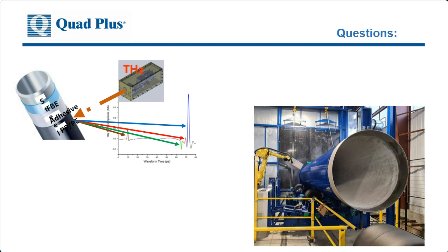Yeah, I think that's generally the case. Obviously with the metal pipe that we're seeing here, it would not be possible to measure the coating on the inside. We have had applications where customers have put, say, a sensor on a long boom that moved into a pipe and looked at the inside of it. But that's, of course, limited in length. You couldn't do a 40-foot pipe section like these are with that type of method. But we have gone in 3 to 8 feet, that kind of range, in order to measure the inside.